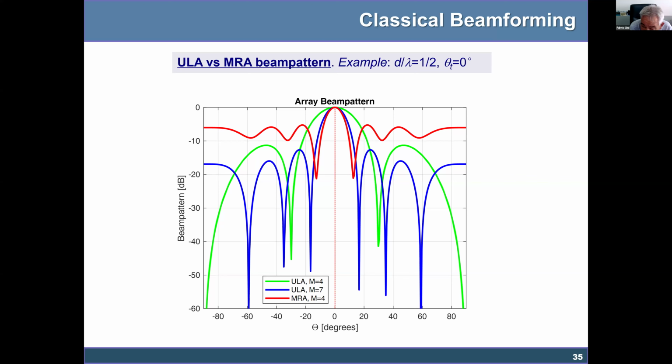No, they don't go down, they go up. When you remove some sensors, the side lobes go up. And the directivity of the array? The gain or the directivity of the array. But the gain is more or less the same. Okay, so the gain is the same, only the side lobes go up and the beam widths are the same. Is that correct, sir?